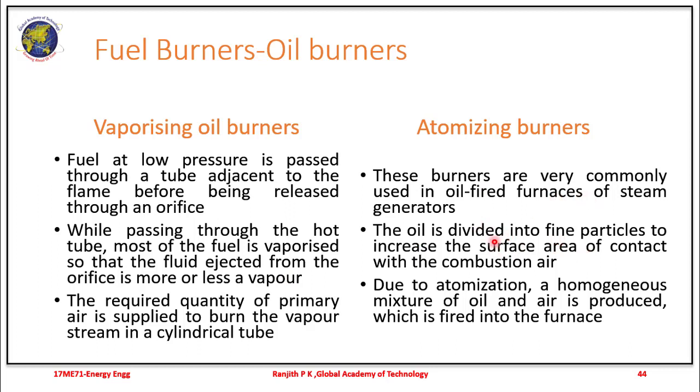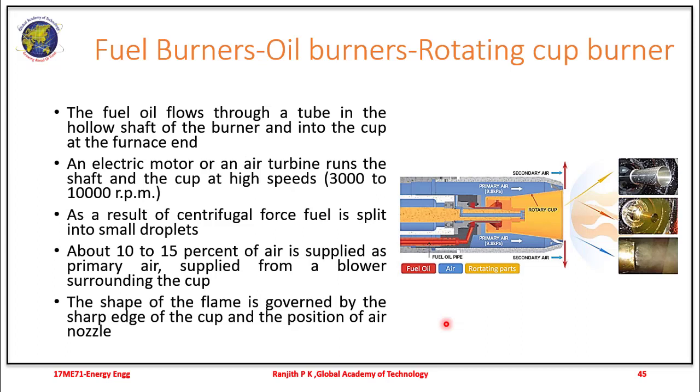In case of atomizing burners, the oil is divided into fine particles, which increases the surface area of contact with the combustion air. Due to this atomization process, a homogeneous mixture of the oil and air is produced, which is then fired into the furnace.